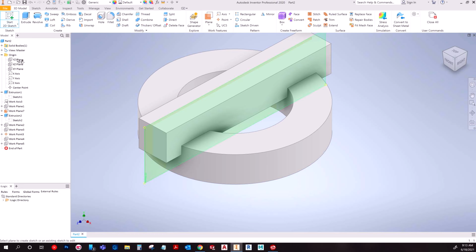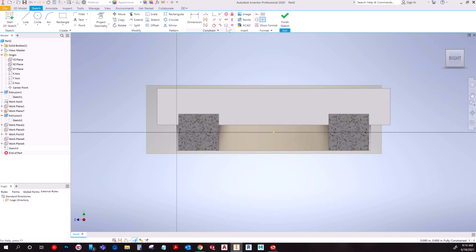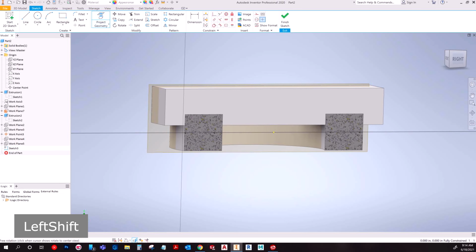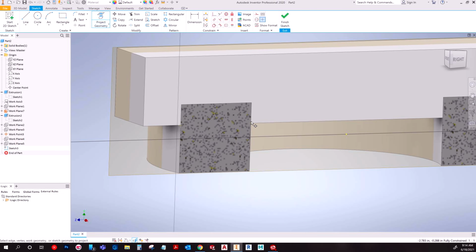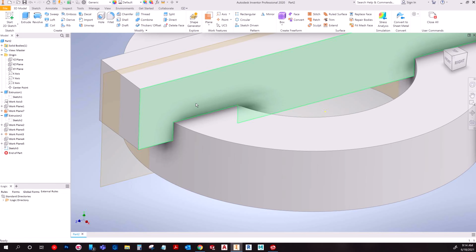I do want to talk about one more thing you could do. I'm trying to think of something I can draw. Basically, you can use sketch geometry as well. So say I were to sketch and do a slice graphics. I could choose this point right here, and this point and this point. Do I want this 3 point? Yeah, it'll be fine. I'm just trying to show an example, but I could make sure the sketch visibility is on, and then I can choose that sketch geometry as well.